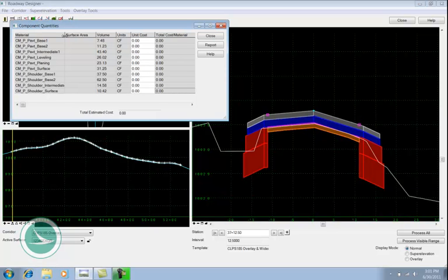In the, I guess what would be July 15th, 2011, here in a couple weeks, our Design Resource Reference Center update, I've made some changes to our components and our levels. Our component names were generic for the pavement layers and the shoulder layers. Just component or CM underscore P underscore pavement 1, pavement 2, pavement 3, 4, 5, and 6. Same thing for shoulders, shoulder 1, 2, 3, 4, 5, 6.